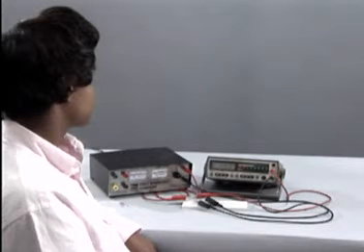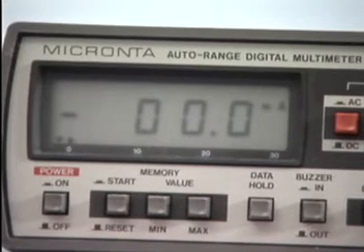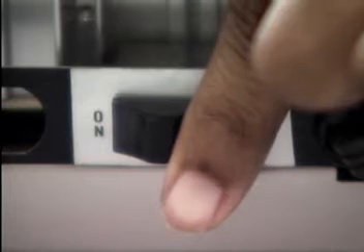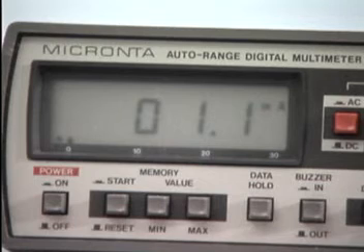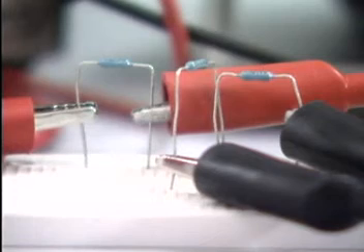Remember, to measure current, the ammeter must be connected directly into the circuit, in series. Now turn on the power supply. Notice that the ammeter is reading 1.1 milliamps. This is the same as the total current. If you repeat this procedure for each resistor in the circuit, you'll discover that the current through each resistor would be consistent. 3 conclusions can be drawn from this demonstration. 1.